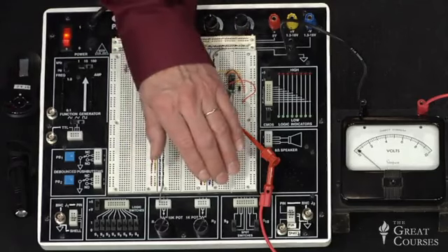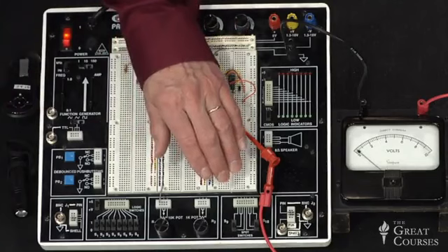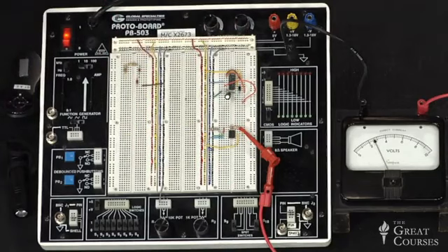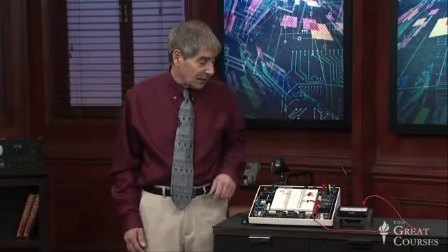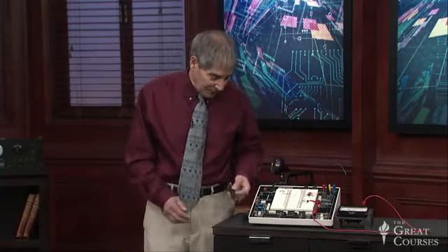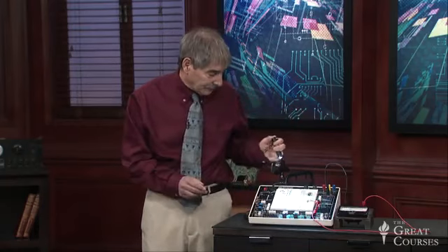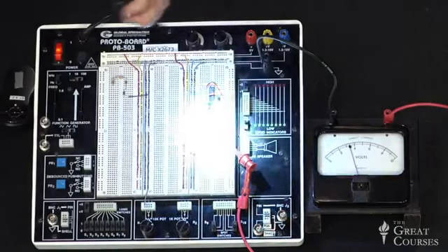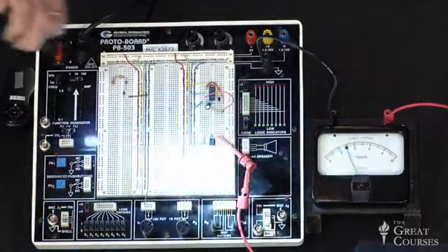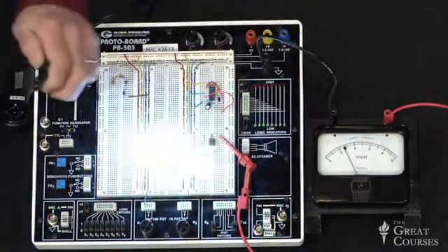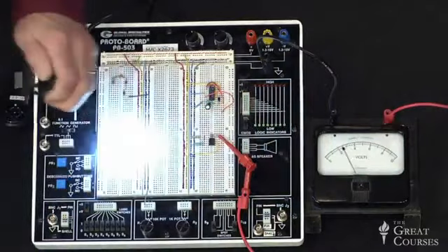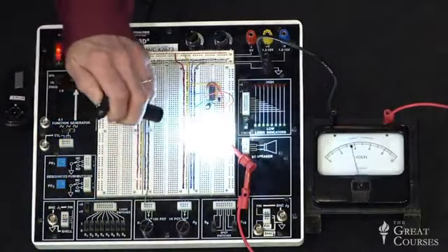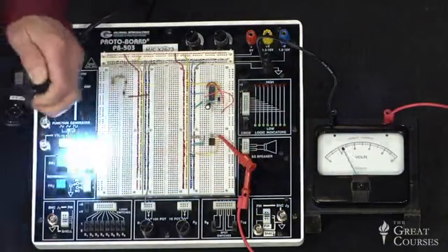If I put my hand over the transistor, you can see the voltage go down. Right now, the transistor is responding to the ambient light in the room, and it is producing a significant voltage, about 3 volts at the output. And if I take a flashlight and turn on the flashlight, you can see that that voltage goes up. We don't have as much variation as we might like because we've got such intense studio lights. I could perhaps increase that by changing some of the resistor values, but there we have it.